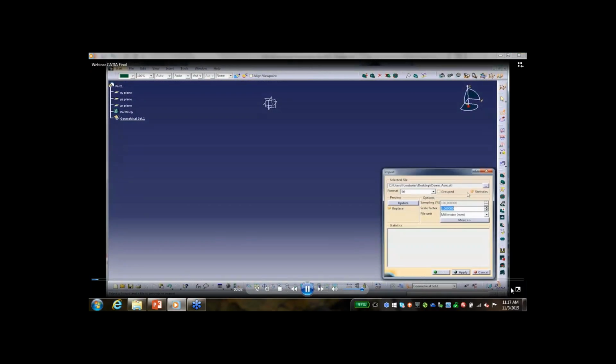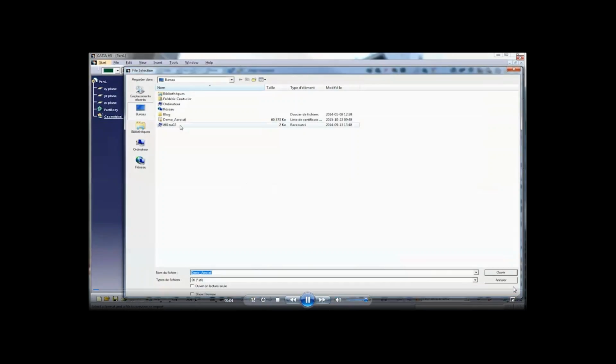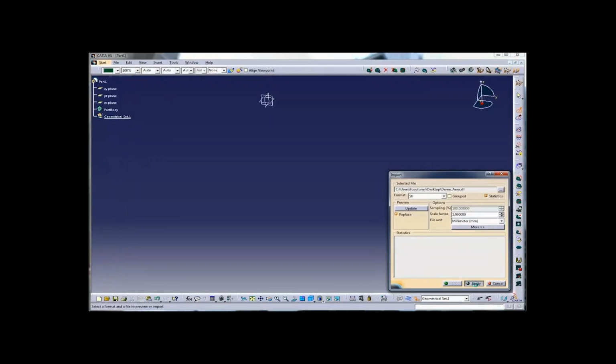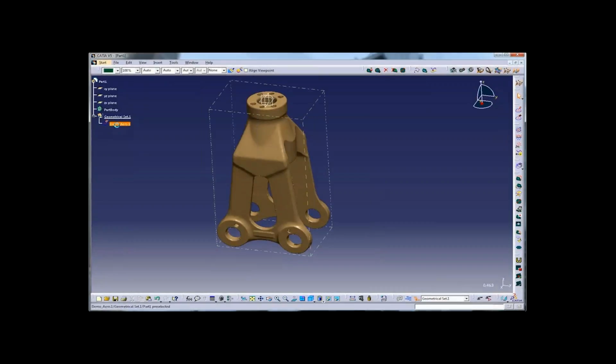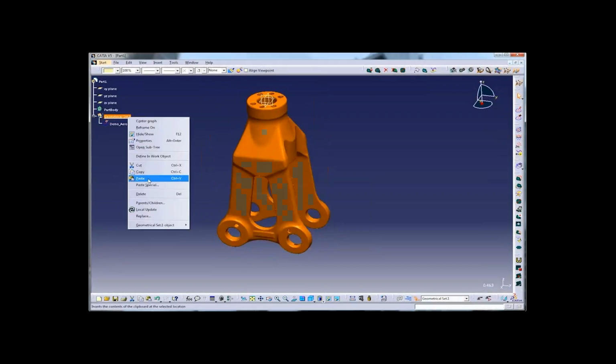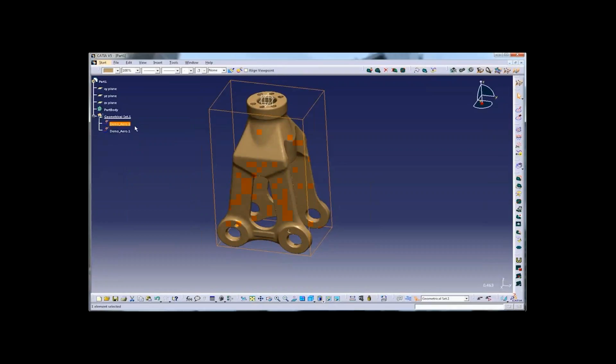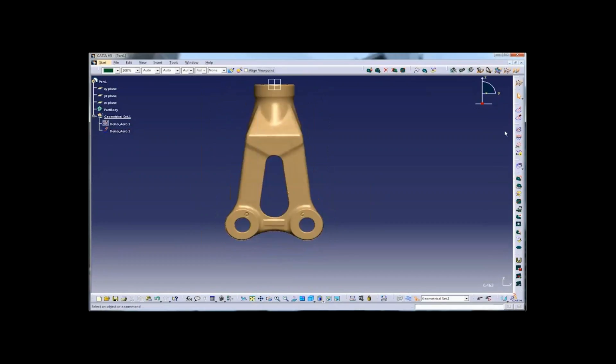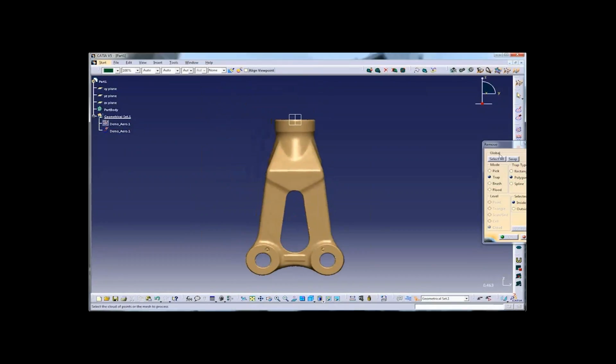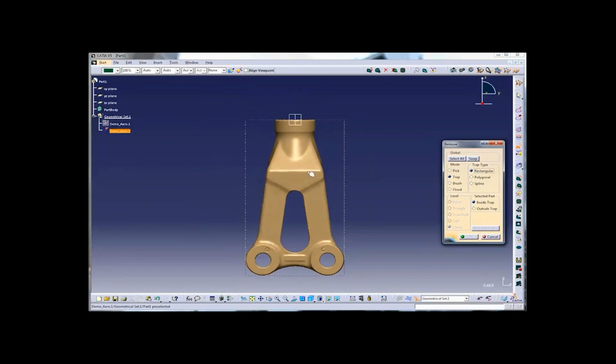So here I'm going to first start by importing my mesh file. Like Frank said, it's a .stl file, and it's a symmetrical file, and it's good practice to copy this original mesh, as all of the other operations you'll do on it cannot be undone. So if you delete something, which I'm going to do like that.